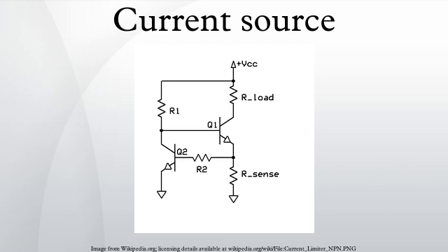The output part of the simple current mirror is an example of such a current source widely used in integrated circuits. The common base, common gate and common grid configurations can serve as constant current sources as well. A JFET can be made to act as a current source by tying its gate to its source. The current then flowing is the IDSS of the FET. These can be purchased with this connection already made, and in this case the devices are called current regulator diodes, or constant current diodes, or current limiting diodes.